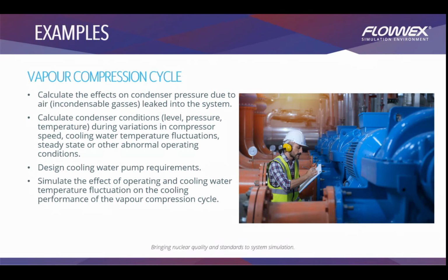There are already inbuilt components in Flownex that make it very user friendly for anyone who's planning to use Flownex as well, because all this calculation is done in the background of Flownex. So you'll be able to calculate the effect of condenser pressures due to the vapor leak in the system, or we'll have the levels changing in the condenser, how that affects the pumping requirements, and how the operating conditions or the cooling water temperatures fluctuating will affect the cooling performance in the vapor compression cycle as well.